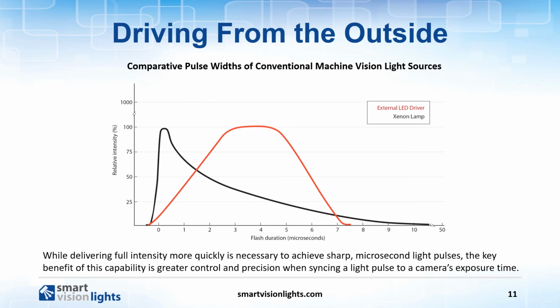Conventional LED systems designed for high-speed imaging can deliver pulses in the same microsecond duration using external controllers. Importantly, however, the physics of such systems introduces inescapable latency issues that dull the edge of the square pulse shape. The longer the cable, the greater the impact from the latency. Even a 1 or 2 foot cable connecting a driver and light source will impose significant parasitic impedances that contribute substantially to system jitter and extend the rise to full intensity.